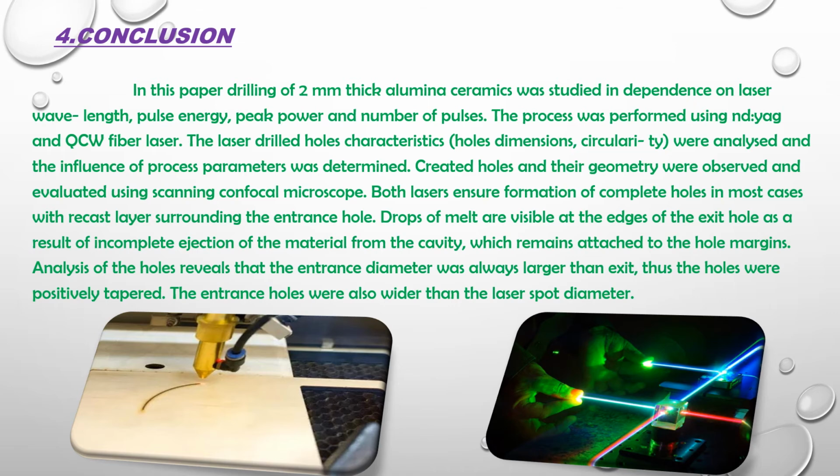Drops of melt are visible at the edges of the exit holes as a result of incomplete ejection of the material from the cavity, which remains attached to the hole margins. Analysis of the holes reveals that the entrance diameter was always larger than the exit, thus the holes were positively tapered. The entrance holes were also wider than the laser spot diameter.